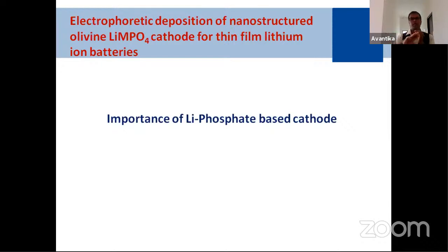Okay. So here I want to explain cathode materials. In cathode materials, there are three types. One is called oxide materials, the second is phosphate-based materials, and the third is vanadium-based materials. Years ago, I already mentioned that in 1990, Sony discovered this secondary battery, the lithium-ion battery. At that time, they used oxide-based material, for example lithium cobalt oxide, as the cathode material for that device. In that, the maximum voltage they achieved was around 3 volts.